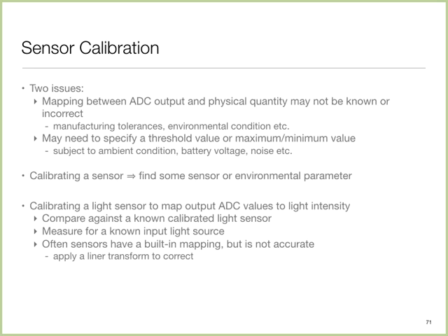So there are a couple of ways you can calibrate. One way is to compare the output of your sensor against the output of a good sensor, often called a gold standard. There is some reference standard sensor and we compare against that. The other is that we have some reference input. A signal generator generates a precise signal, we subject our sensor to that, look at its output, and calibrate against it. Oftentimes sensors come built in with a reference signal generator, and they make use of that.